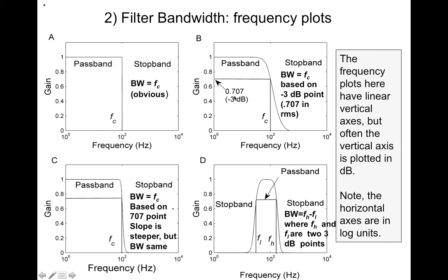So a more realistic kind of filter is not one that has this immediately square shape, but basically one that begins to transition at some level, at some frequency below that 100 hertz that you would define as your bandwidth, or as your, what we would call cutoff. In other words, meaning above that level, you don't consider the components to be present in the signal or the filter, and below that level you do.